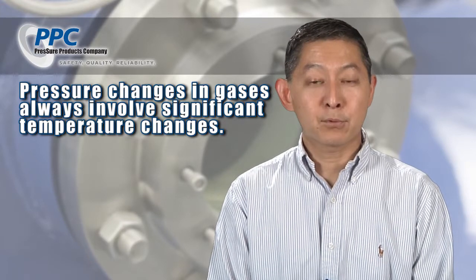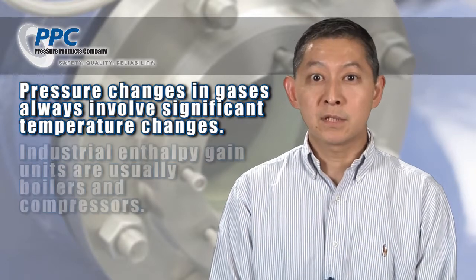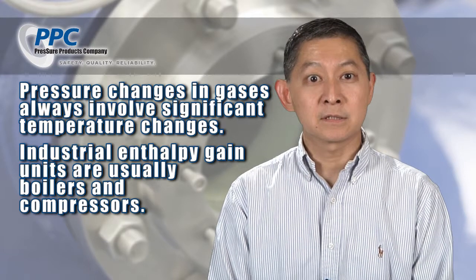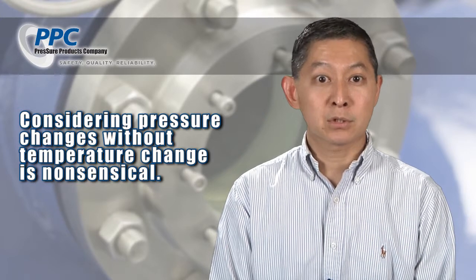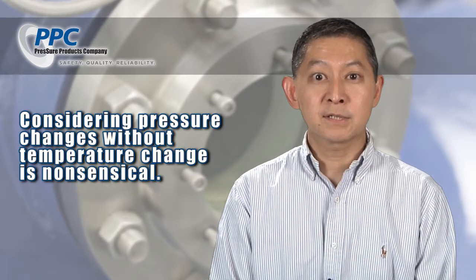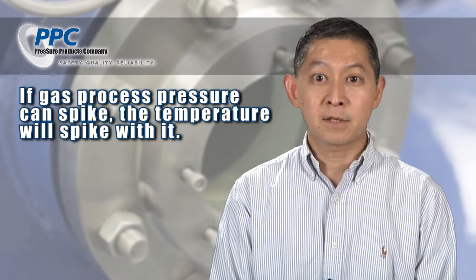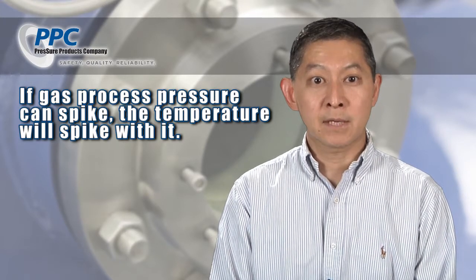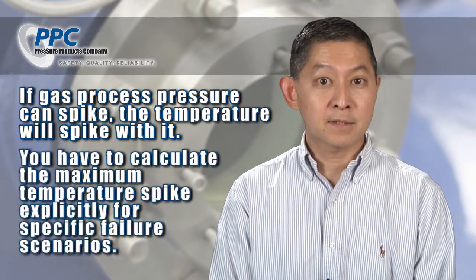If your process involves high pressure and high temperature gases, you have to consider the two parameters together. The two industrial units that impart enthalpy to fluids are compressors and boilers. In both of these cases, the temperature and pressure of the exit stream are coupled to each other. You cannot raise the pressure without simultaneously raising temperature deterministically. So if you have one of these processes and you decide that you need a pressure safety factor, you also need to explicitly calculate where the temperature is going. In other words, if your enthalpy gain device somehow creates a pressure spike that lasts more than a few seconds, you will also be seeing a corresponding temperature spike.